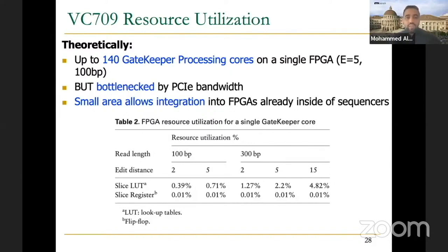Sometimes you cannot apply the VCC or the ground to a large number of gates, and that's specified or controlled by the total critical path or the worst delay in any of the input signals, for example. So you may need to use pipelining techniques to reduce this critical path, or you reduce the number of replications. These are all challenges when you implement a parallelized algorithm in FPGA, or you would like to fully utilize all resources you have in the FPGA.